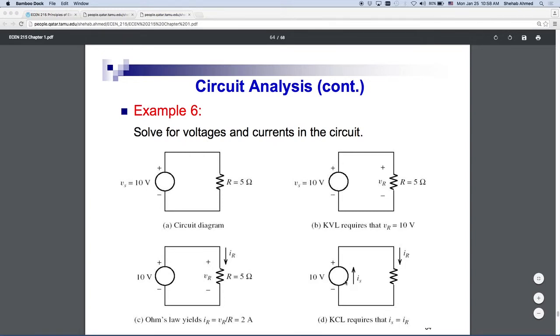And we also know that this is a source. It's a source that is supplying power. For a source that is supplying power, current will go out of the positive terminal, right? Any element that is supplying power, current will be flowing out of the positive node. So it just confirms the fact that we also chose the proper direction for the current to the resistor, right? So this is a very simple example, but it helps us review these notations that we talked about, right?